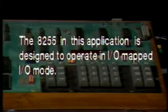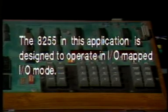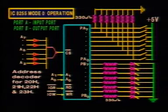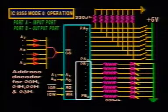The 8255 in this application is designed to operate in I/O mapped I/O mode. The I/O address of the control word register is 23H. The move immediate instruction loads the control word into the accumulator of the CPU. The out instruction transfers the control word to the control word register at address 23H. After these instructions are executed, the device is programmed. Port A will now operate as input port and port B as output port.